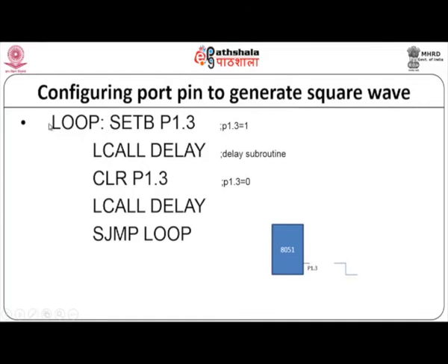Now loop is a tag I have placed for jumping, and SETB P1.3. SETB tells that I am setting the P1.3 pin equal to 1. Now I have set it to 1. LCALL delay: this is a subroutine called for making a delay.